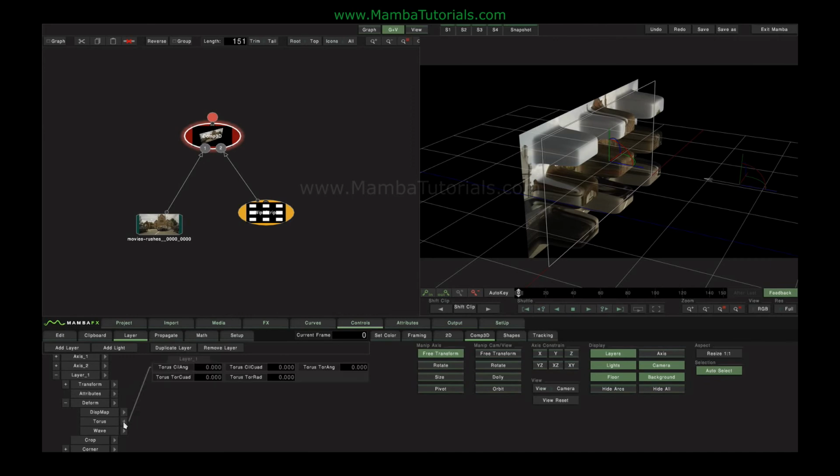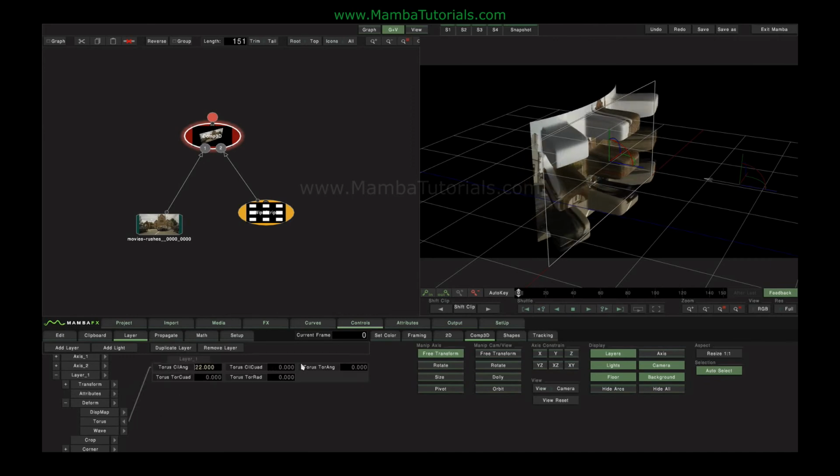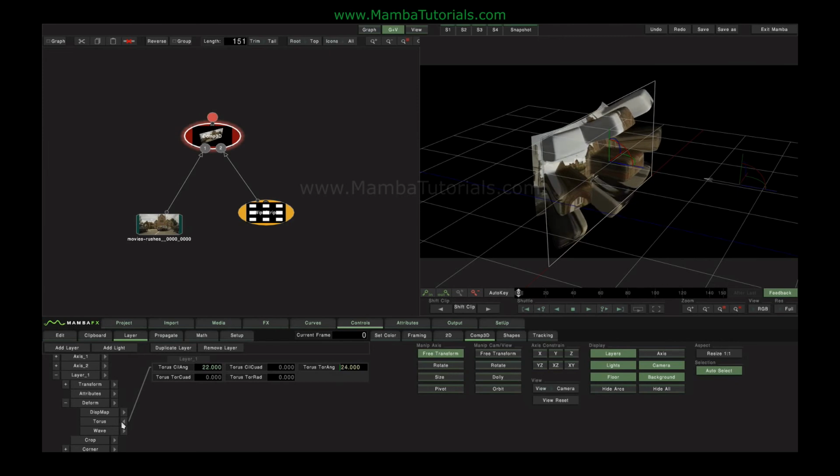You can combine all these 3D deforms in order to make whatever weird shape you want to make. You'll notice the object has a basic level of light and shade on it, and that comes from our ambient lighting, which is set to 1/3 in each channel at the moment. If we wanted to remove the shading altogether, we would set these to 100. Even if you just rotate a plane away from direct view, it'll start to shade. If you don't want that, just switch these to 100 and you won't get any shade.